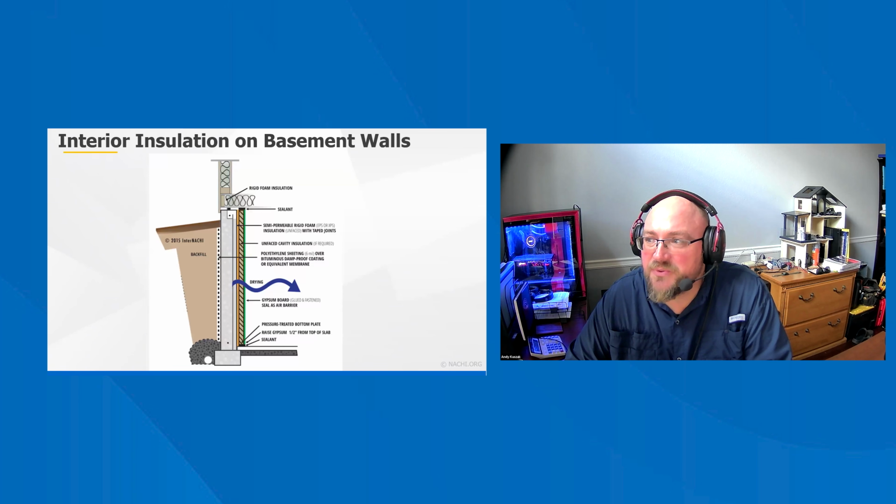The insulation to use when finishing a basement is rigid foam insulation board. That type of insulation will allow the foundation wall assembly to dry inward, away from the foundation wall, and toward the interior of the finished basement space. The foam insulation should be vapor permeable. The greater the perm, the easier it is for the wall to dry inward. Because the foam insulation needs to be continuous and sealed at the seams, the insulation should be installed behind the wood framed wall. Additional insulation can be installed in the spaces between the studs.